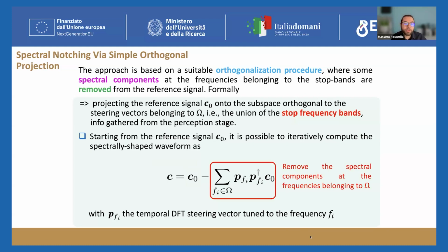In this expression, you can see this term PFI, which denotes the temporal DFT steering vector tuned to the frequency Fi. While this method has the advantage of being computationally efficient, it provides less control over the waveform characteristics than the QC-QP-based approach.